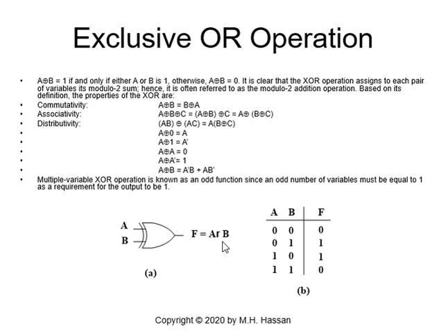Now the exclusive OR has some very significant properties that we would like to look at. A exclusive OR B will be B exclusive OR A. A exclusive OR B exclusive OR C will be A exclusive OR B, then between parentheses, exclusive OR C, which is equal to A exclusive OR, B exclusive OR C.